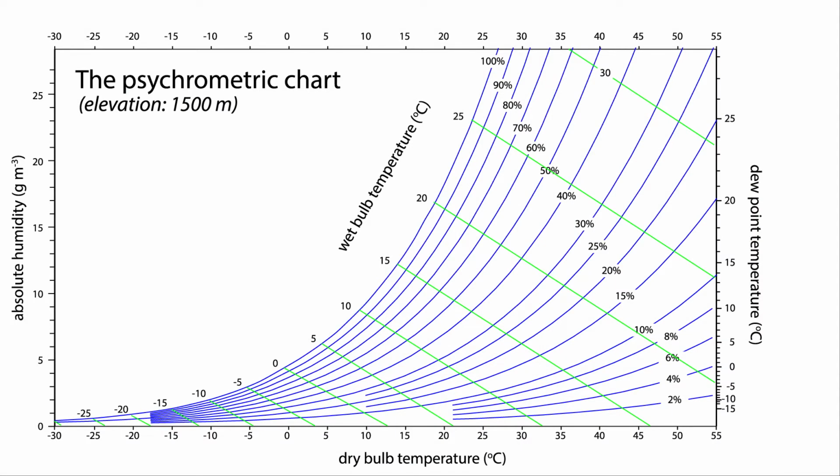A handy way to calculate relative humidity from the temperatures of the wet and dry bulb thermometers of a Sling Psychrometer is to use a psychrometric chart. There are also various kinds of software tools available for free on the internet that you can use to do this, but using a psychrometric chart gives you a graphical view of the results of your measurements. Thus, it's very useful to know how to use a psychrometric chart. Not to mention the fact that the internet is not always available in the field.